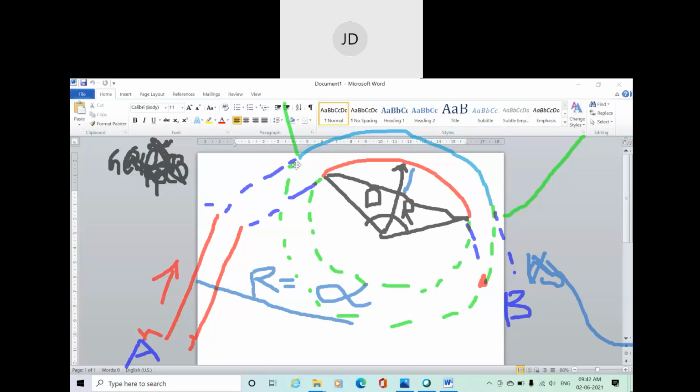And this blue color part, here you can see the blue color part, is basically known as transition curve. And what is the purpose of this transition curve? It gradually increases the value of the gradient and super elevation that needs to be provided in a curve. Regarding super elevation, you already know these things from highway engineering. We are going to discuss super elevation again in the coming classes. So you know this thing, right, about super elevation.